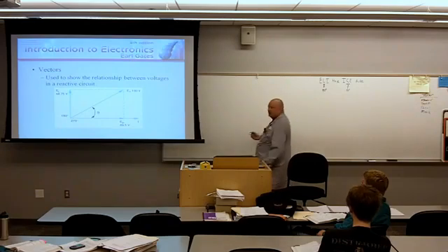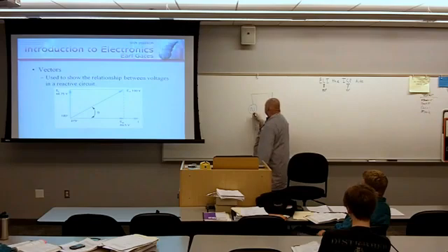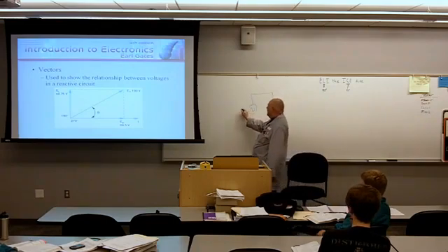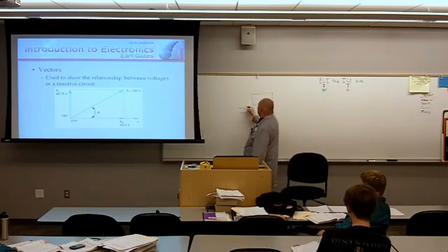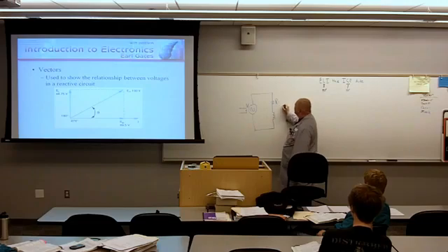So just by looking at this, I could tell what kind of circuit that we're looking at. Okay? If you can't, you may want to draw the circuit, right? So this is going to be an AC series RL circuit. Does that make sense? AC, we're going to have two pieces here. One is going to be the voltage, the other is going to be the frequency. In a series RL circuit, we're going to have resistance, which is going to be measured in ohms. And we're going to have inductive reactance, which is going to be measured in ohms.